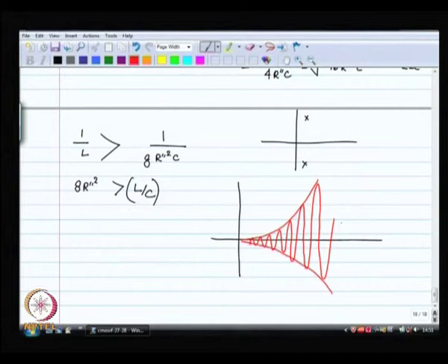Okay. So, this is what happens when the two poles are on the right half plane. Now, unfortunately, we can't have the output of our circuit rising forever, because you have got a limited power supply. Eventually, sooner or later, non-linearities of the transistor are going to come into effect. The system is not going to look like two poles on the right half plane anymore.